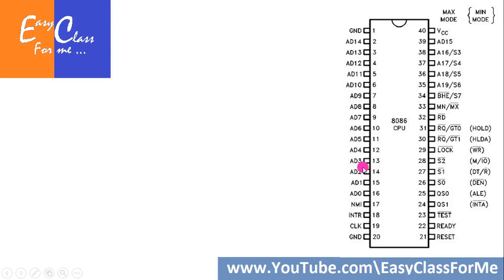So what they have done is, you can see here that AD0 is written, which starts from pin number 16, and AD14 which goes to pin number 2, and then AD15. So from 0 to 15, there are a total of 16 pins which have combined address and data. A stands for address and D stands for data. At one point of time they will be operating as address bus, and at another point of time they will be operating as data bus.